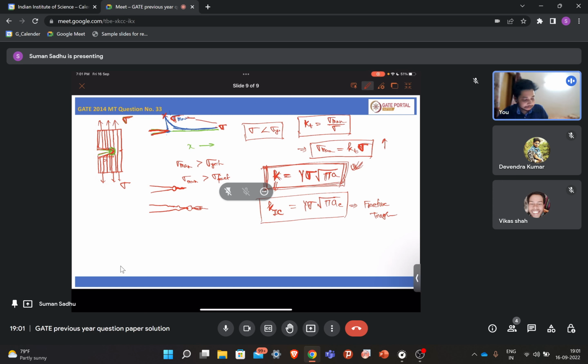So this is the relation between your applied sigma and the stress intensity factor. When this stress intensity factor reaches the critical value, it is called fracture toughness. That means at that critical value, your crack propagation rate will be very rapid and will suddenly lead to fracture.